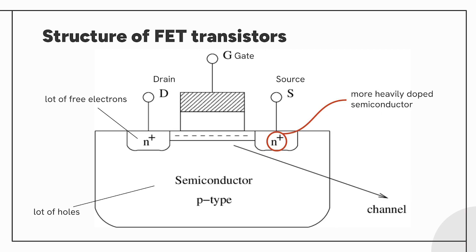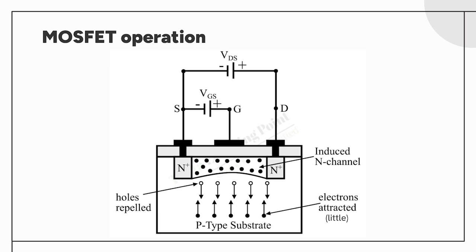Conversely, when plus voltage is applied to the gate electrode, the holes run out, creating a depletion state between the N-type semiconductors. At this time, if plus voltage is applied more strongly to the gate electrode, the very few minus electrons that exist in the P-type semiconductor will gather at the top. And if these electrons continue to gather, they will form a tunnel-like channel, and an electric current will flow between the N-types. In the N-channel MOSFET, this layer is used to make electrons flow.